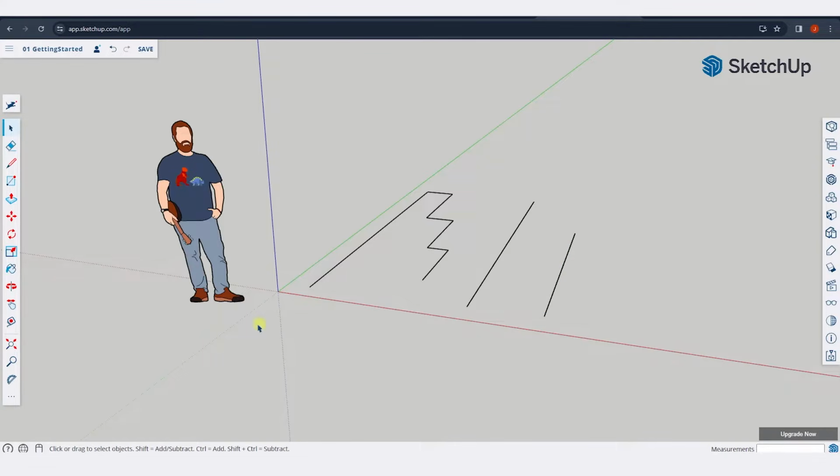in order to verify that it's 9 feet long. Now, one thing I didn't talk about originally is when you activate this tool, or really any tools in SketchUp, I highly recommend that you don't click and drag. So if I tap the L key again, move my mouse over here, and I click and drag, notice what that's going to do is as soon as I let up on this line, it's going to draw the line, right? Well, the problem with that is it doesn't really let me type in the value of the line that I want to put in here.